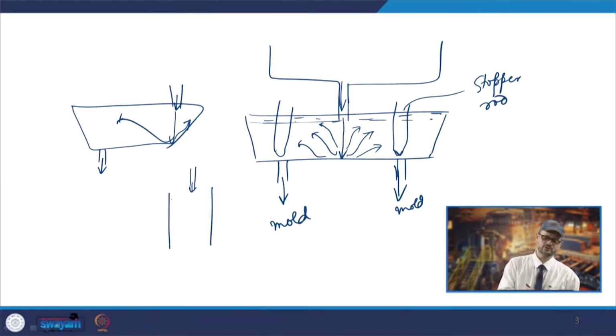So as we have seen, in the case of the mold, when the liquid metal is poured through it, it starts forming the skin, and the shell thickness will go on increasing on both sides. Now, the question is what should be the height of this mold. It has to be such that it ensures there is a skin frozen of certain thickness, and then